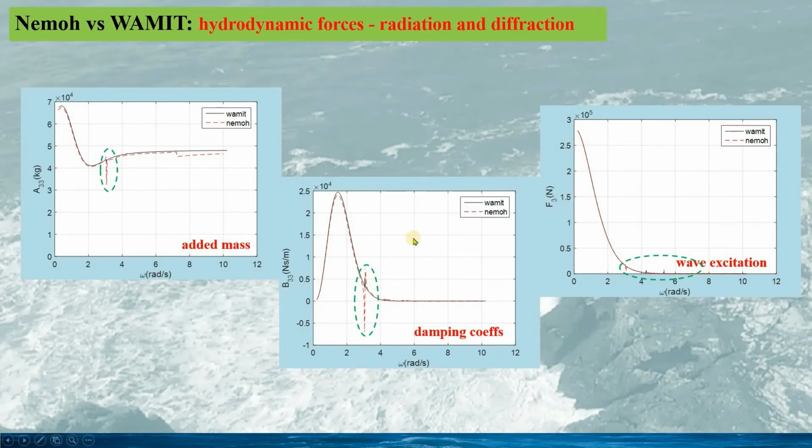Also, such a narrow spike might not cause significant problems in structure motion or wave energy conversion. And from the damping coefficient, we can see the max radiation damping happens close to the resonance frequency, about 22 kN·s per meter.